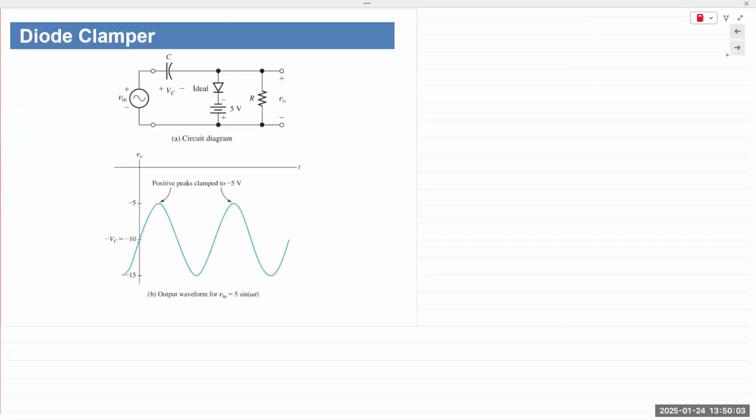One of the most common examples of a Zener diode clipper is taking two Zener diodes, connecting them back to back or in parallel, and using it in a surge protector. One Zener diode each would conduct in the positive and the negative half cycle. Anything larger than 120 volts will be clipped off. So it works as a voltage regulator in both directions and clips off any surge voltage that comes in.